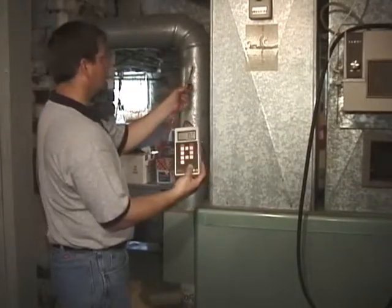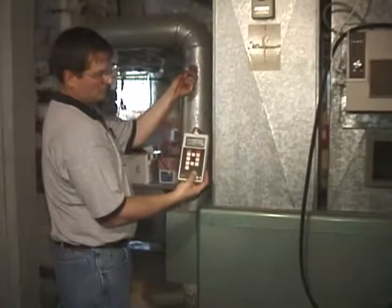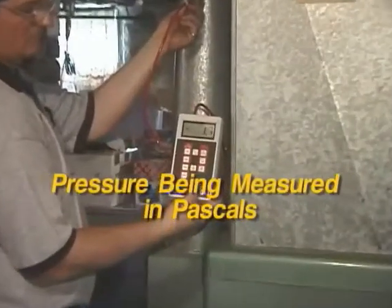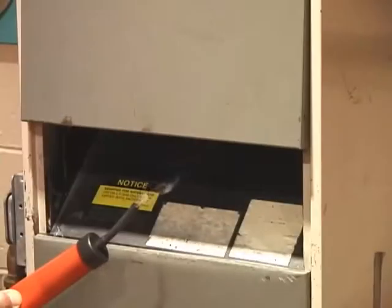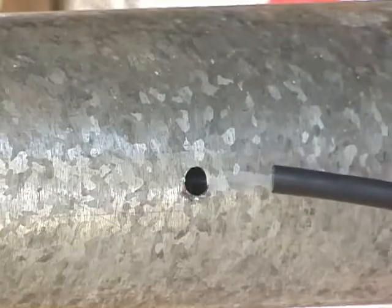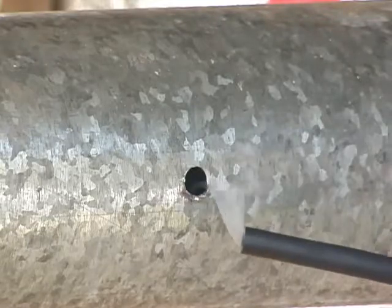A negative vent static pressure simply means that the pressure inside the vent is lower than the pressure in the combustion appliance zone, or CAZ. This negative pressure, or suction, is what draws both the combustion byproducts and dilution air from the combustion appliance zone, past an open draft hood, diverter, or damper, and on out through the vent system. If there were a crack or hole in the vent connector at this point, air in the combustion appliance zone would be drawn in there as well.